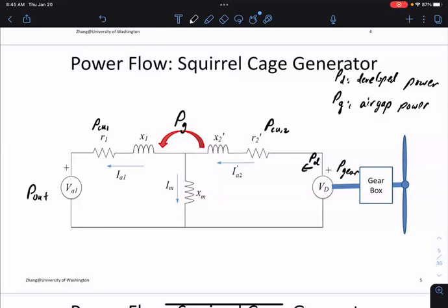If S changes a little bit, it will be very, very sensitive. Technically, this works with any non-zero R2. But in practice, you want R2 not to be very small. You want some R2 there to generate high enough voltage to have power flow.